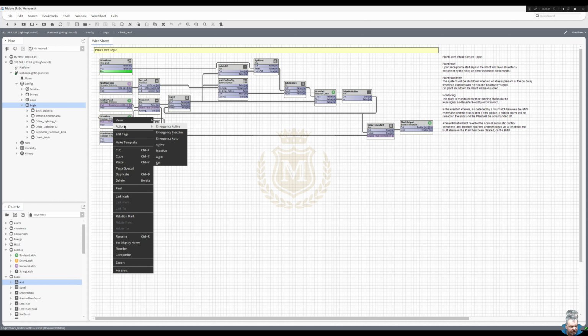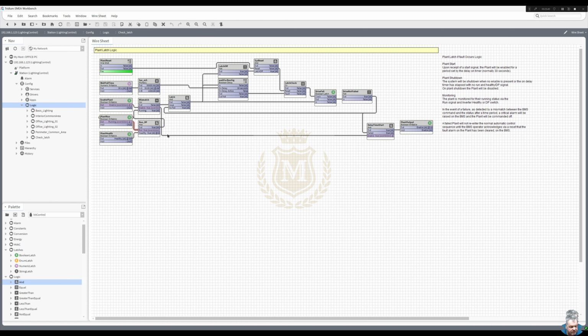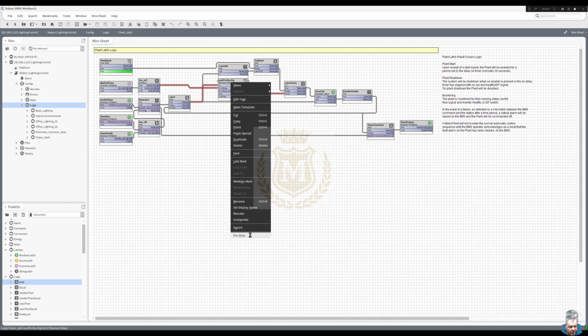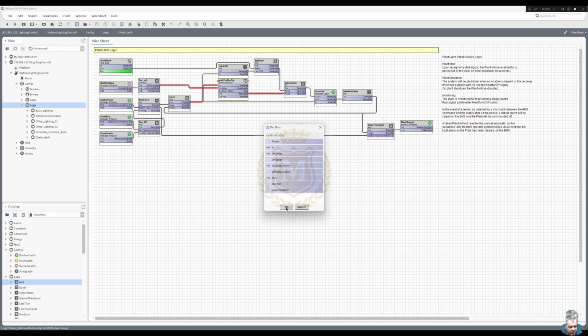If I take the plant run off, that then from my XOR gate is giving me a true. That true is going up into this, so I put that timer on. I'm timing 30 seconds and that out. So let's get rid of the out not. So the out will go true. Put a true into there, it's an OR gate. Put a true into there, which just puts that output in, so it's latched that output as a true because I've already was in a true there.